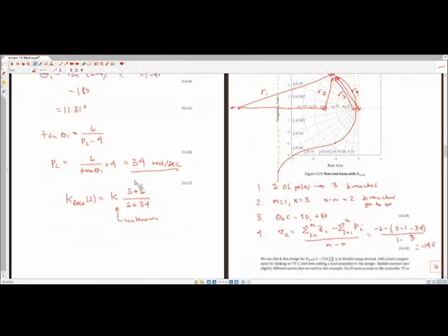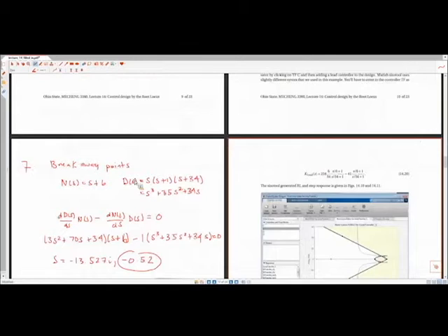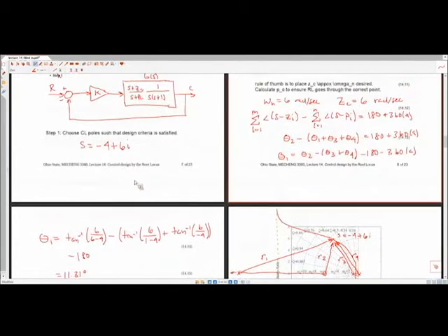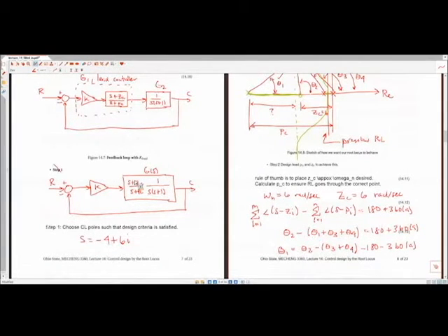We can then calculate the magnitude of g of s. Keep in mind we have to understand the innate gain of the system. The innate gain of the system is actually just 1. This is now in pole zero form. This wouldn't necessarily be true; you could have plants with a different innate gain, but this one has a 1 out front, which makes it a little bit easier.